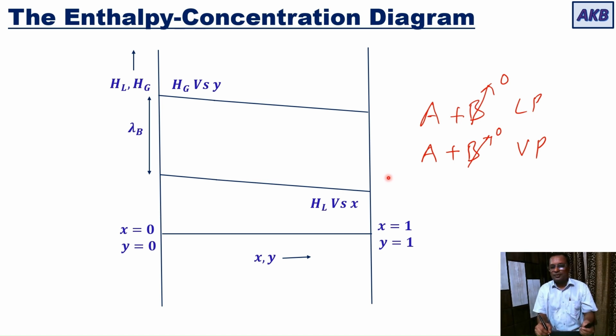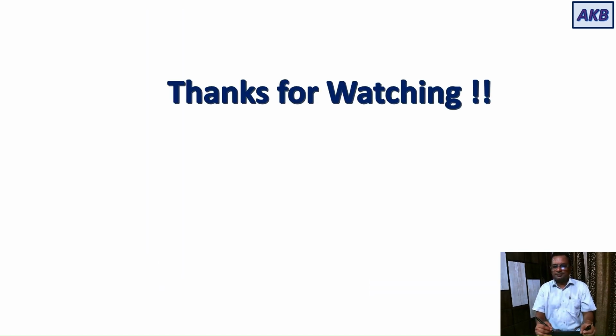So this is how the enthalpy concentration diagram is plotted. I have discussed it in my earlier video on the energy balance. If you have any doubt, if you have not understood any concept in this particular case, you can mention that in the comment section. So this is the second diagram, the enthalpy concentration diagram, which will be used in the Ponchon-Savarit method. So with this, I end my discussion for this small introduction to the Ponchon-Savarit method.